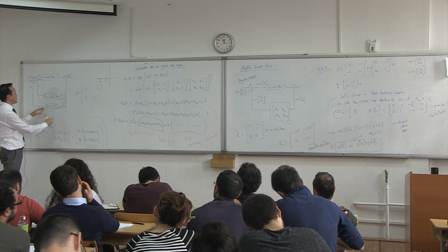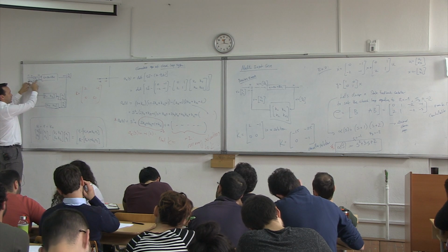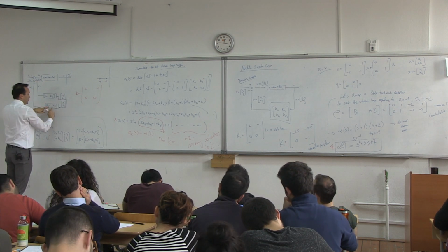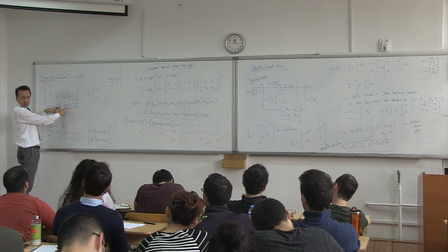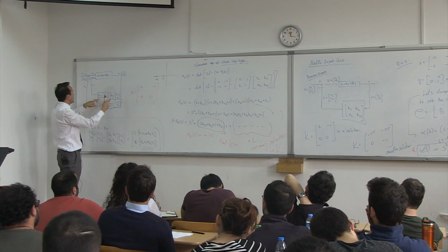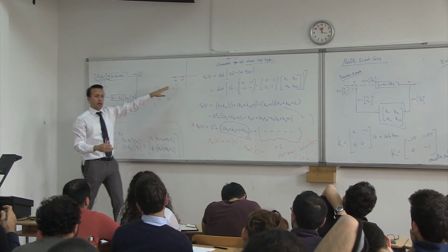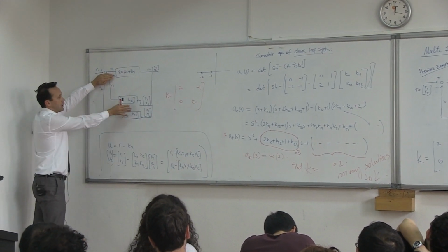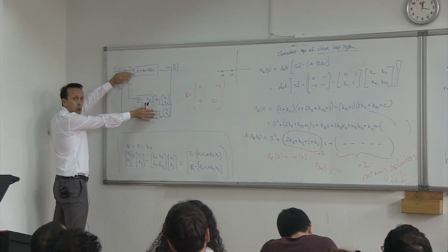It simply means that there is no feedback for the second control. Right? K21 and K22 will be equal to 0, so no feedback here. And you adjust this feedback. So which means you can actually achieve this by only using one control. You don't need to have a second feedback loop at all.